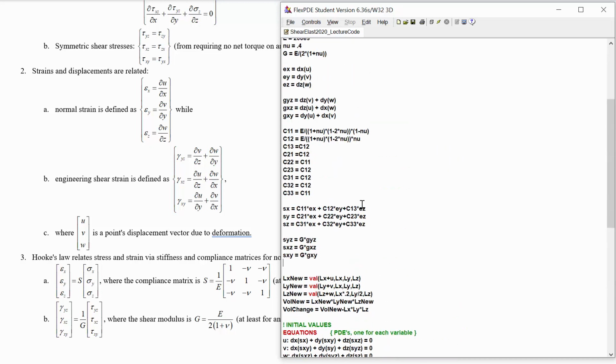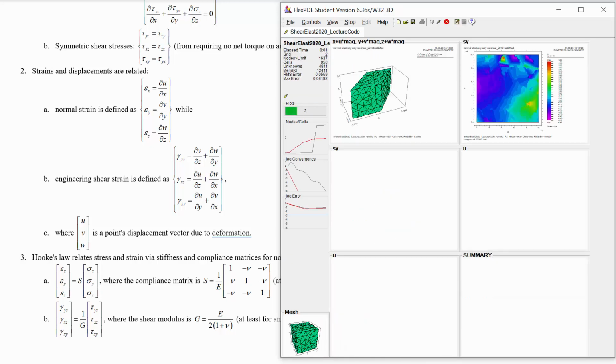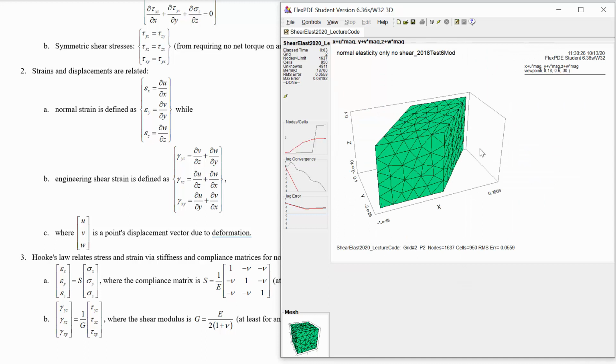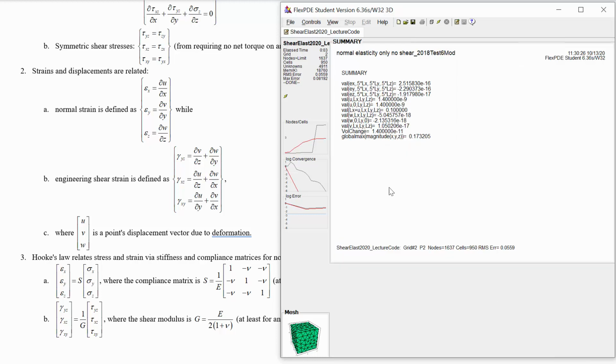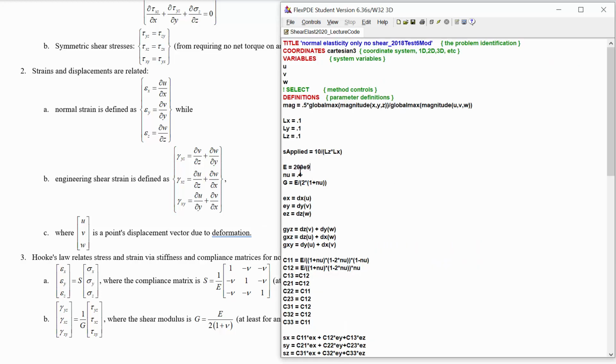Okay, so let's see what we get. Wow, that ran a lot better and gives us something like we would have expected. Again, we're magnifying the displacement a lot. It's actually not nearly as much as it's showing in here. And the x displacement at the far right corner looks like it is 1.4e-9, which is about half of what we would have expected from our calculation. Oh, wait a minute. Not 140e-9, 1.4e-9. That's way off. Okay, so now we want to go check what we did. We didn't put in the right Young's modulus.